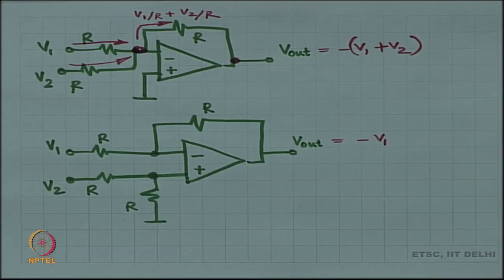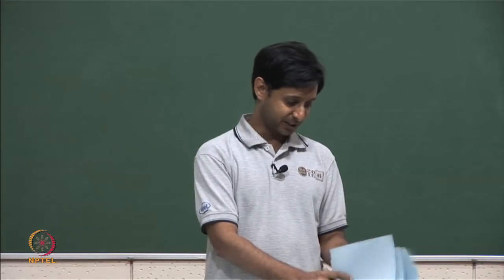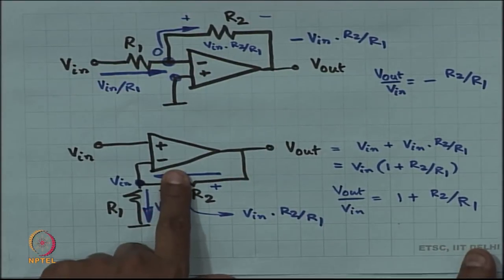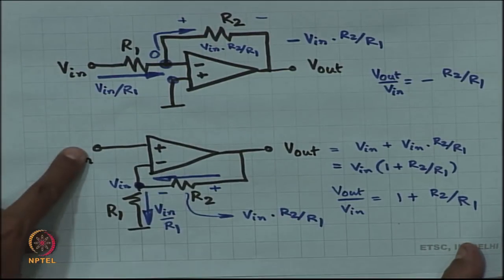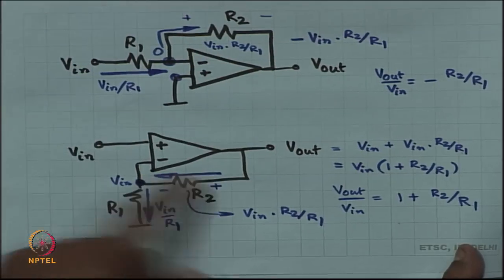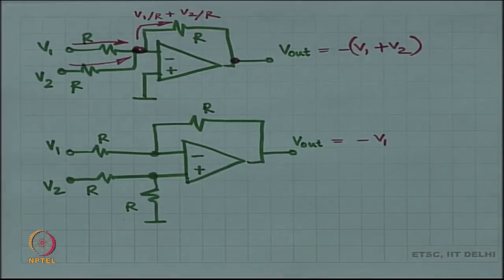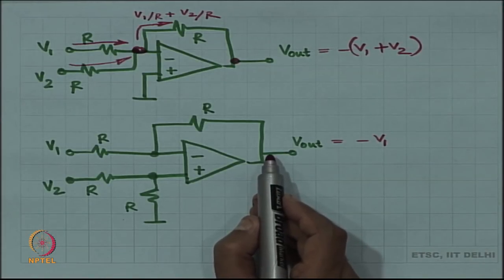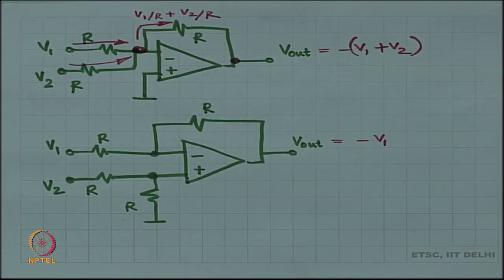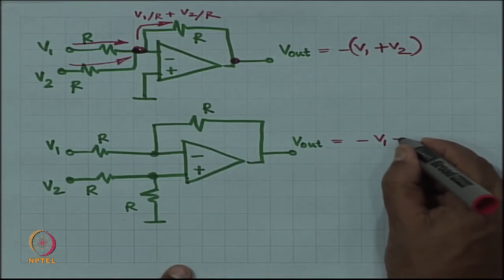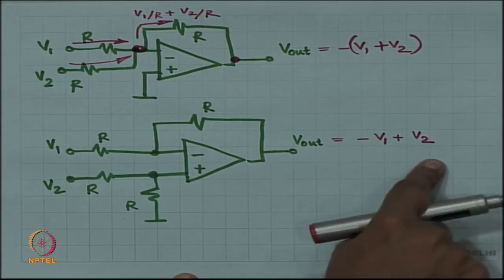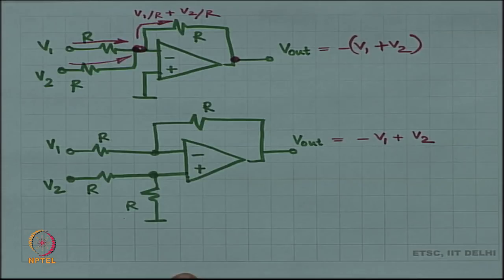Right, we are talking about the good old circuit, this good old circuit. Over here I have got V 2 by 2 and I have got R and R over here. So, it has a gain of 2, and if it has a gain of 2, then the output is nothing but V 2, because V 2 by 2 through a gain of 2 becomes plus V 2. And because of superposition, these two quantities come together and add up.